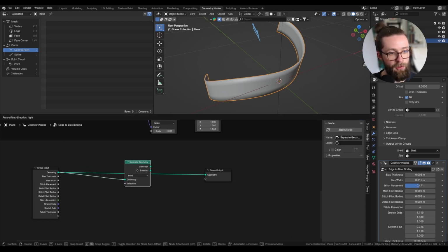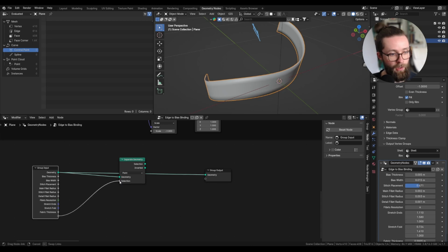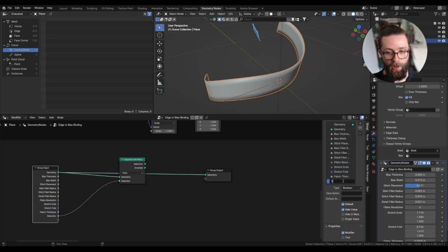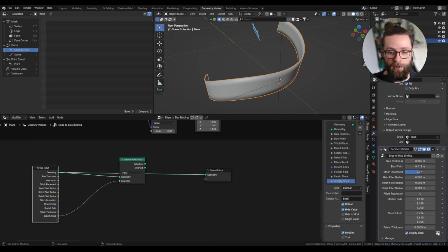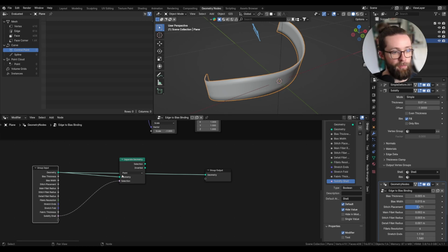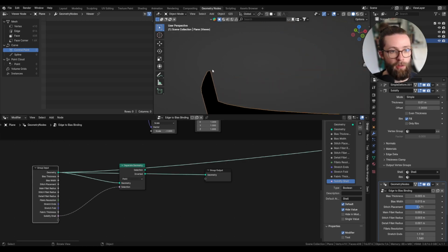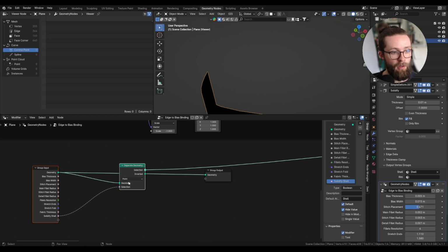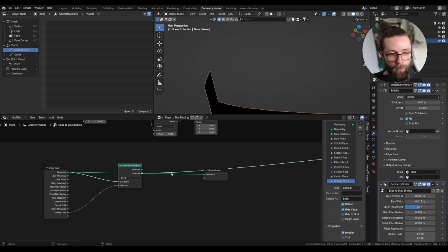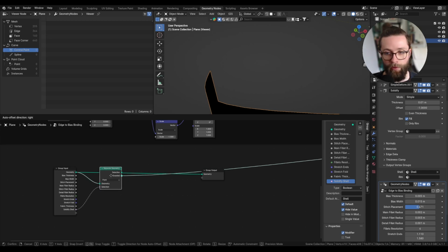I'm going to add a first separate geometry node, and for the input, which I'm going to rename solidify shell, with the default attribute called shell. Now in my modifier tab, I can switch this to attribute and select the attribute shell I just created, which gets its data from the solidify modifier. So from this, instead of getting the full geometry, I'm just getting the base geometry before the modifier on the inverted output. So this is where we are going to get our geometry.